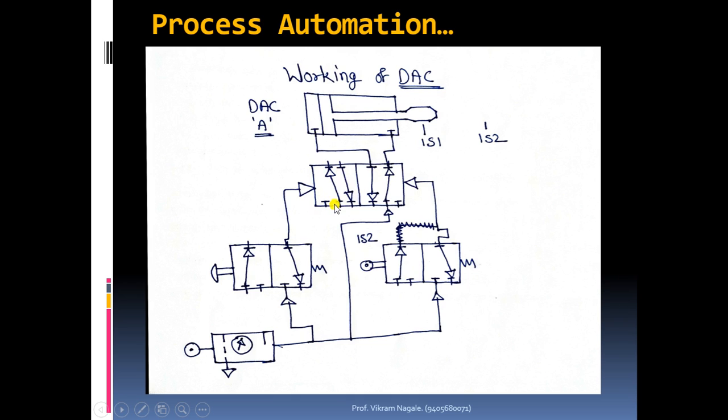Okay, so 1 is taking to port 4, and since we are connecting this left to left and right to right, what will happen, this left will take the air to the left side of this piston, and it has to apply pressure on the left side of the piston, and the air which is initially present on the right hand side of the piston, that is open, that will be open to the atmosphere through these linings of the valve.